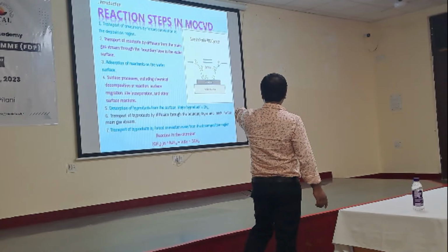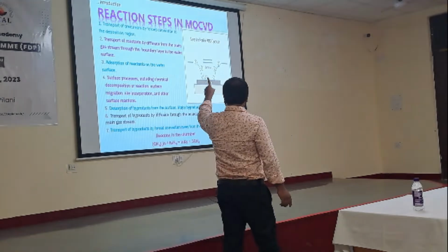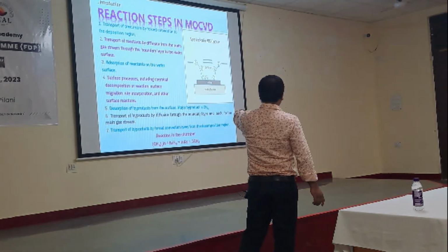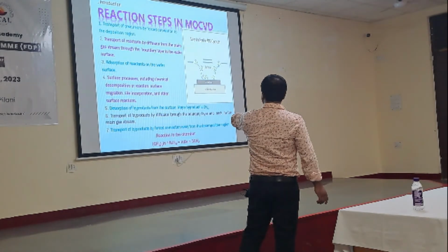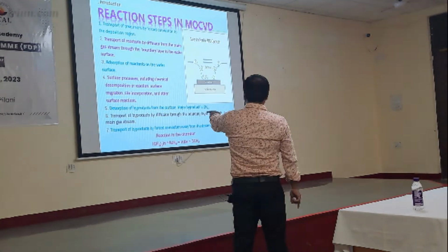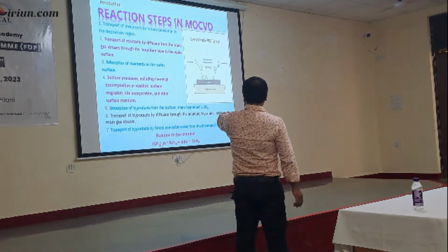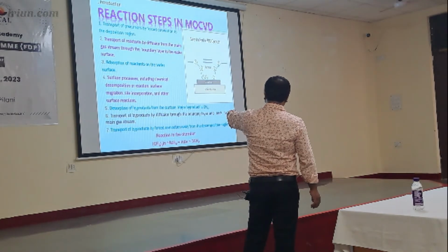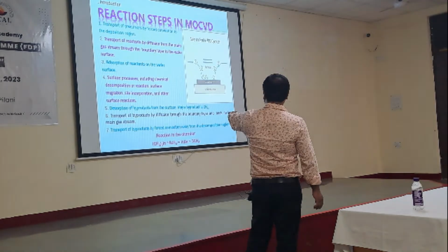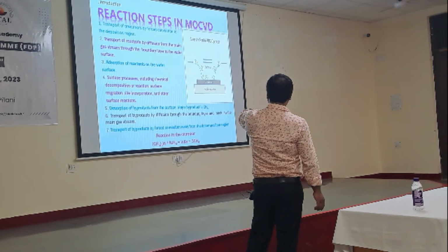Okay, because I need indium arsenide. That's why Trimethyl indium, In(CH3)3: that is your organic compound, indium is metal. I call it metal organic because this species contains both metal as well as your organic. That's why metal organic. So because I need indium arsenide, you have to take In(CH3)3, trimethyl indium, plus arsine equals indium arsenide plus CH4, methane.